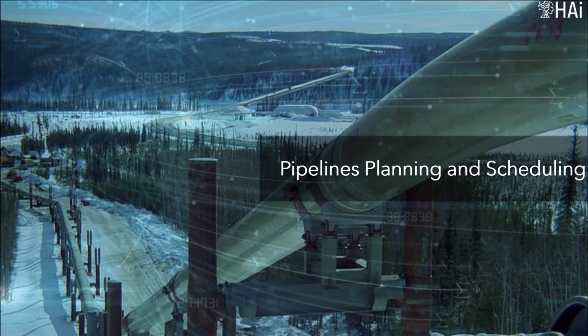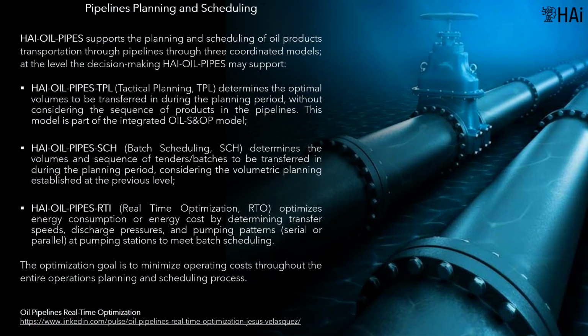Pipelines planning and scheduling. HI supports the planning and scheduling of oil products transportation through pipelines using three coordinated hierarchical models. Tactical planning determines the optimal volumes to be transferred during the planning period, without considering the sequence of products in the pipelines. Batch scheduling determines the volumes and sequence of batches to be transferred during the planning period, considering the volumetric planning established at the previous level.